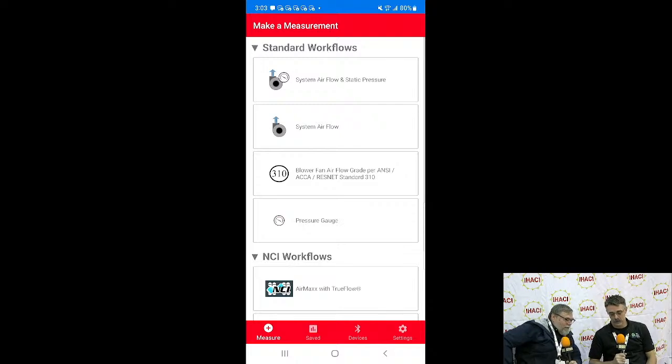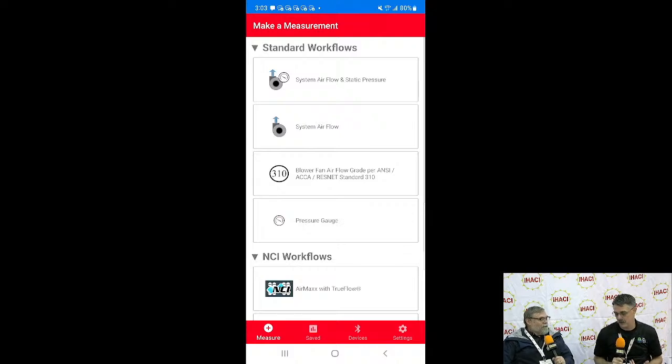We're back. So what that allows us to do is to utilize this tool to forecast, hey, is this new piece of equipment going to work on this duct system? Now, we might combine that with a good load calculation on the house to make sure that we're sizing everything properly. Maybe we want to do a little bit of work on the house so we can potentially downsize a system. But it tells us whether or not the static pressure and airflow is going to work on that duct system. And if it's not, then you can do whatever you need to fix that.